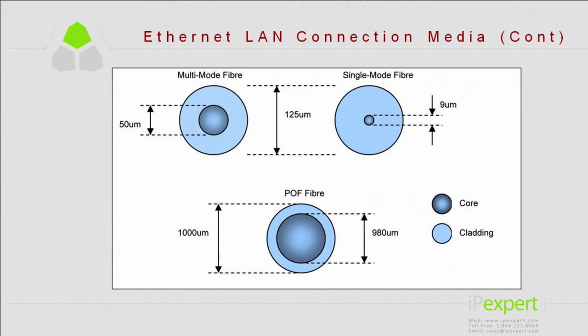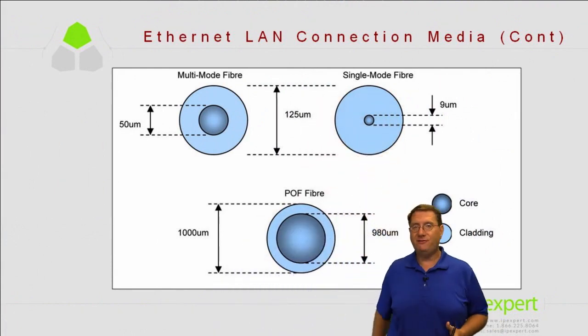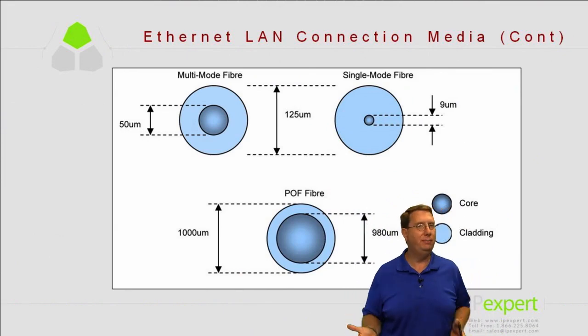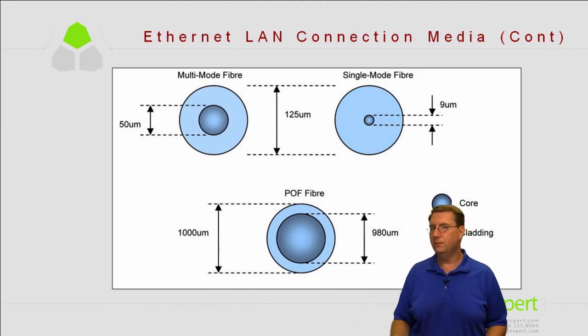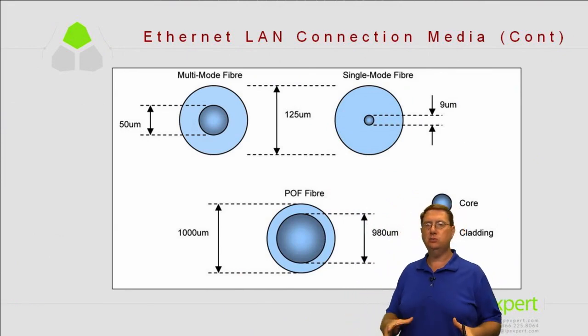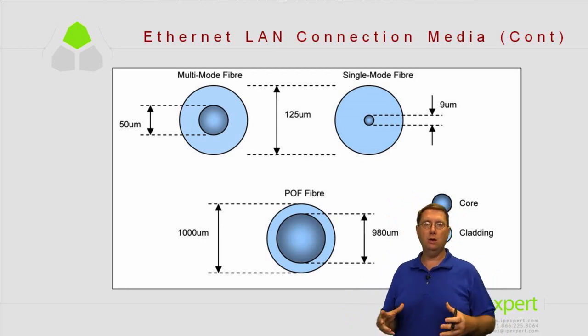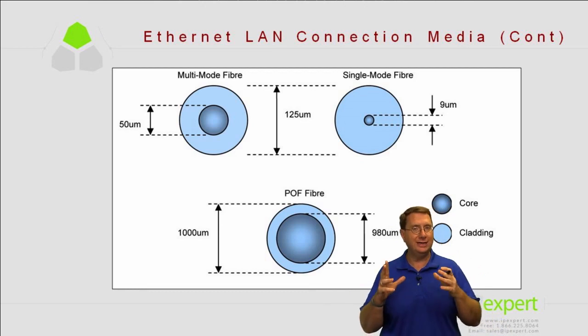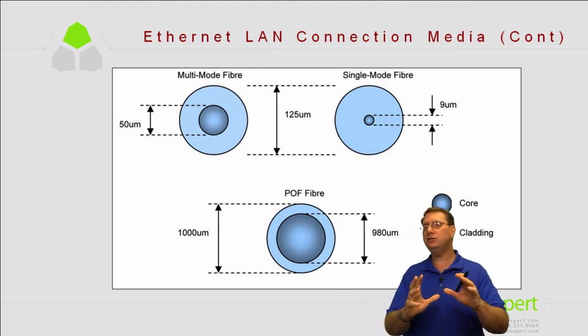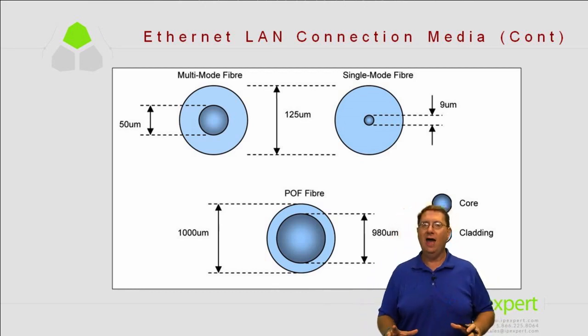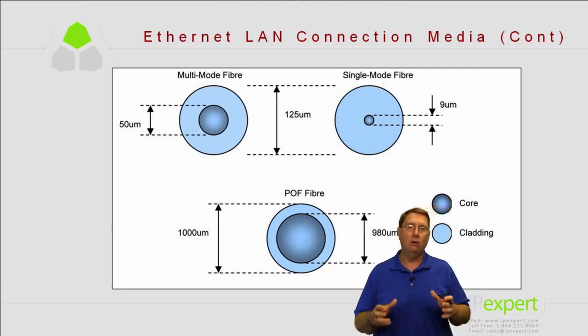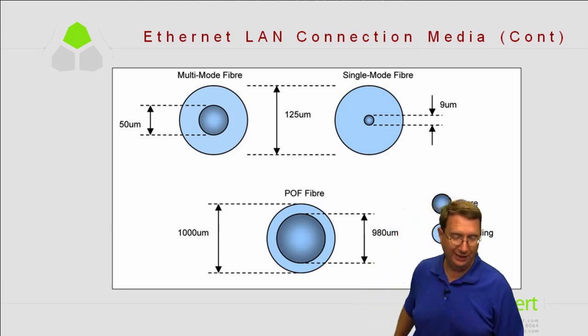Now, the other solution we have here is fiber optics. Fiber optics are not the end-all be-all. They're not the perfect solution. In fact, we're going to find a concept called a macro bend. When we start working with fiber optic cabling, we need to understand exactly how it's constructed so we can understand the significance of how we deploy it, and its impact.